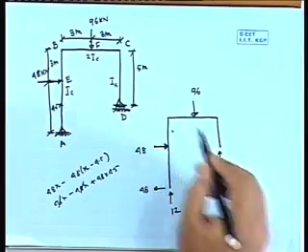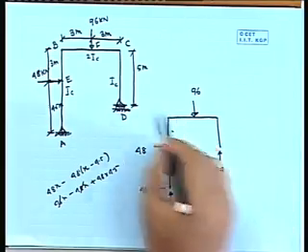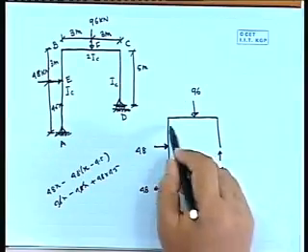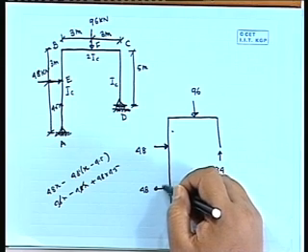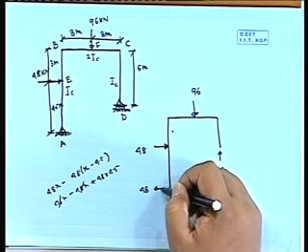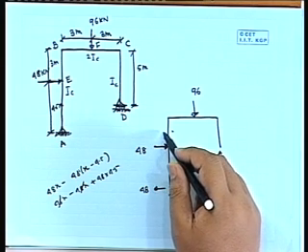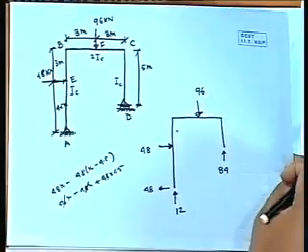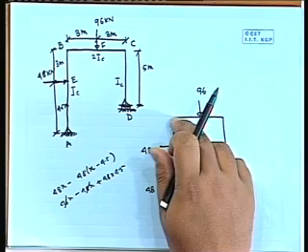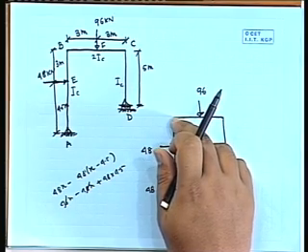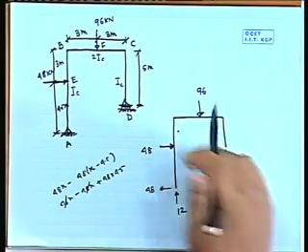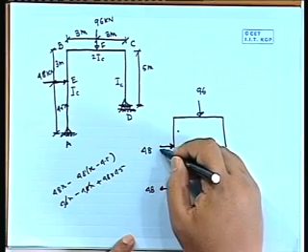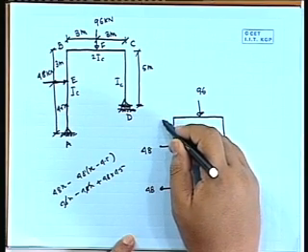So again you just come to this figure. So here x we are starting from here, right? From here x will start. So this is the B. Now this 48 and this 48, they will produce a moment of, just now we have, 216 will be the moment that will be there up to this, right? So if I draw a bending moment diagram, it will be just like this, then it will be constant.